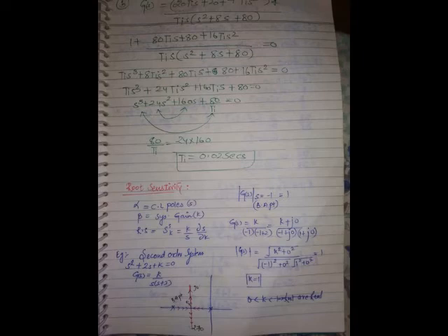Next, 16th question. A PD controller is used to compensate a system. Compared to the uncompensated system, the compensated system will have higher type number. Is that correct? No, because it has no effect on type and order. Reduced damping? No, damping increases.